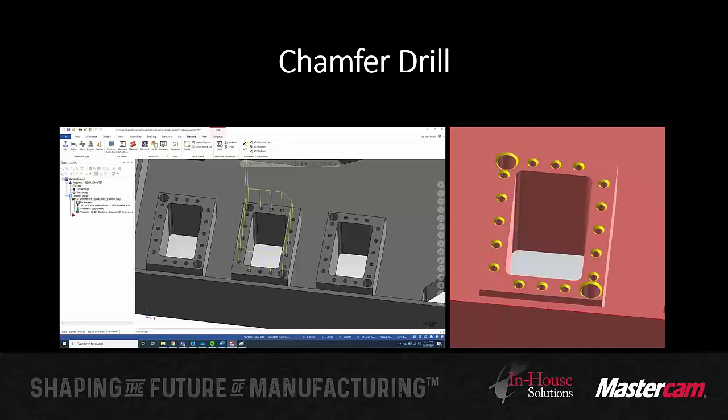What's actually going to happen is, if by chance I select, for example, a 1/2 inch chamfer drill and I have a hole that's 5/8 big, obviously I can't just do a drilling operation to spot a 5/8 hole with a 1/2 inch chamfer drill. So it's just going to skip over that hole. If you've selected any hole that's too big for that tool, it'll skip over it and continue on with the rest. It's not going to error out or not do anything. It's smart enough to say, I recognize I can't do this one. Likewise, if it's too small with the size of the land, it'll skip over those holes and continue on. So that's the new chamfer drill operation, making your life a lot easier than having to utilize that drill operation every time.